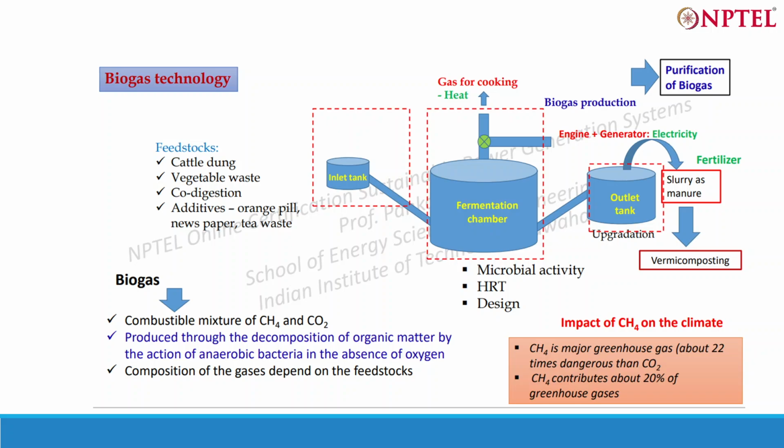One of the key requirements of these digestive chambers is that they should work in typical temperature zones, and these temperatures have to be maintained throughout the period of operation of the digester. It is the thermophilic zone when you are going for 50 to 60 degrees Celsius, and the mesophilic zone when you are going for 30 to 40 degrees Celsius. Both zones of operation have pros and cons attached, but generally in research papers and the scientific community, the focus is more on the mesophilic zone because the temperature is low and can easily be achieved and maintained.